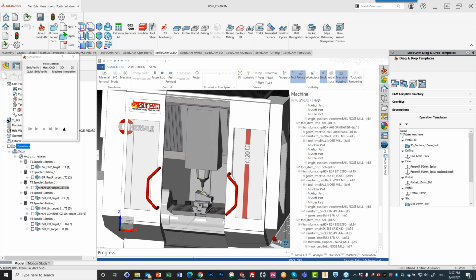Now, one question is: is there anything that indicates to the programmer that a change was made by the ShopFloor Editor? The answer is no. At this point, the machinist should always be in contact or leave a note or something like that to the programmer that a change was made. At this point, there is no way to know unless he actually looks at the program.